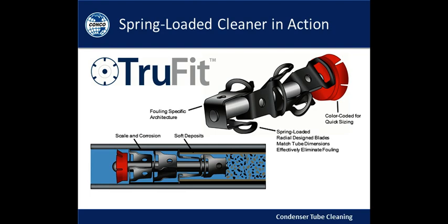By now, then, you've seen the video of the C4S tube cleaner traveling through the tube. The tube cleaner was inserted into the tube, and it was propelled with 300 psi water pressure. The radial design blades put pressure on the ID of the tube to remove the corrosion product and the deposits, and all the deposits are removed out ahead of the tube cleaner.